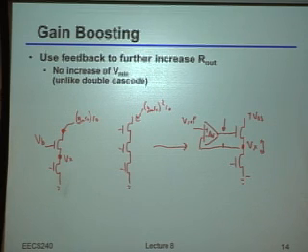So because of that, you can basically say the equivalent gm is also 1 plus Av larger than it was before. If you think about it, all put together, that means the output impedance of that structure is 1 plus Av times gm ro, I'm sorry, times gm ro times the original ro. Does this make sense to everybody?